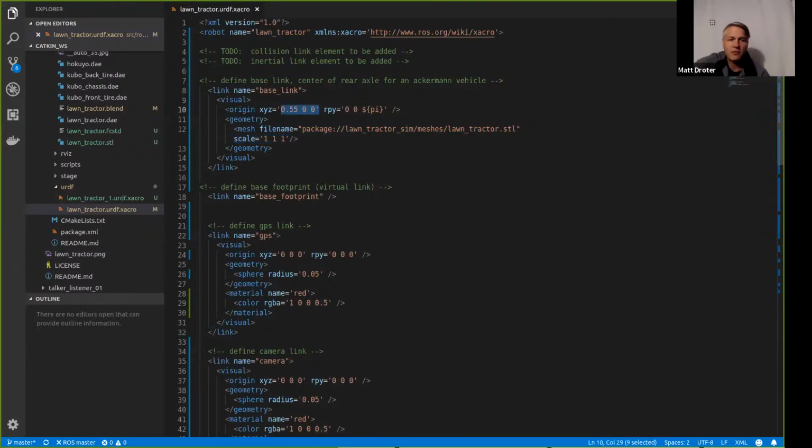That's what it's showing. Sam, on this origin, that's kind of where you hang the image around the base link. Sometimes it makes a big difference. You can just change that 0.55 to 5, and the image will be 5 meters in front of the origin or base link. If you put the Z at 5, it'll be 5 meters above. So it's just where do you want to hang that image in relation to the base link, which is 0, 0, 0.